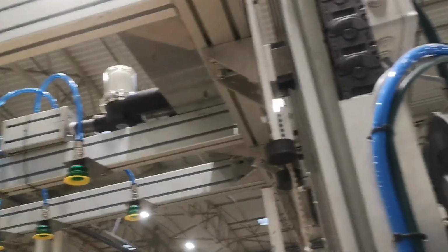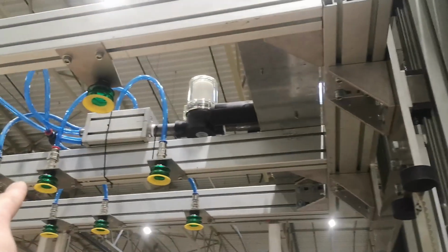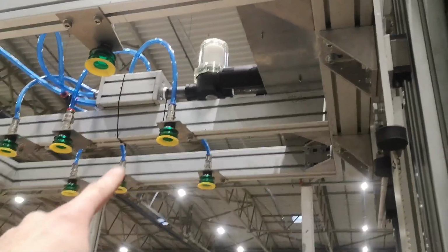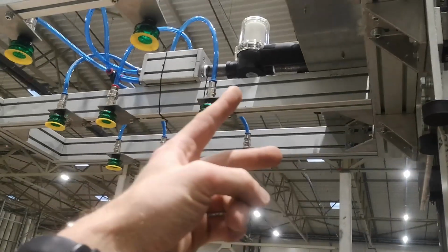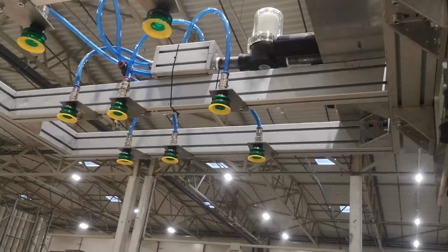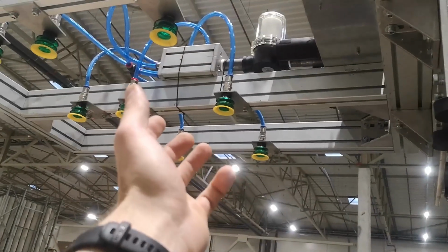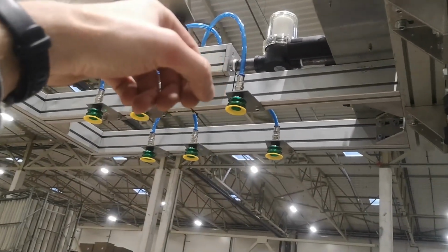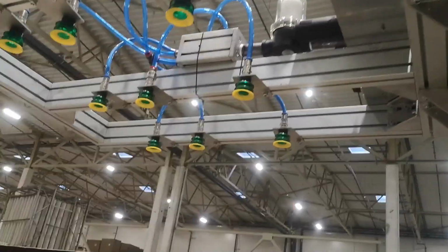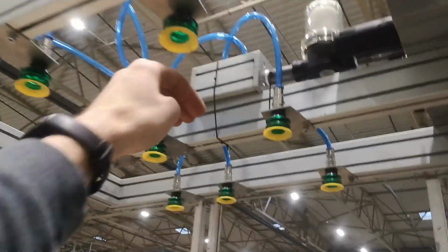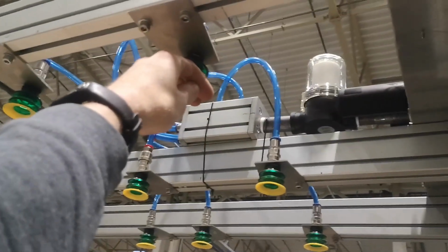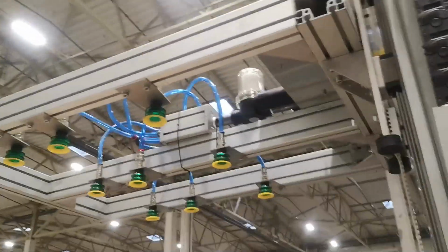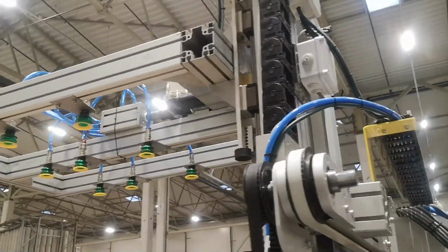On the tool we have vacuum sections, and 2 valves, one for activating the vacuum and another to activate the compressed air pushing through. So when I grip and need to release, I activate another valve to push back, so it works much faster this way.